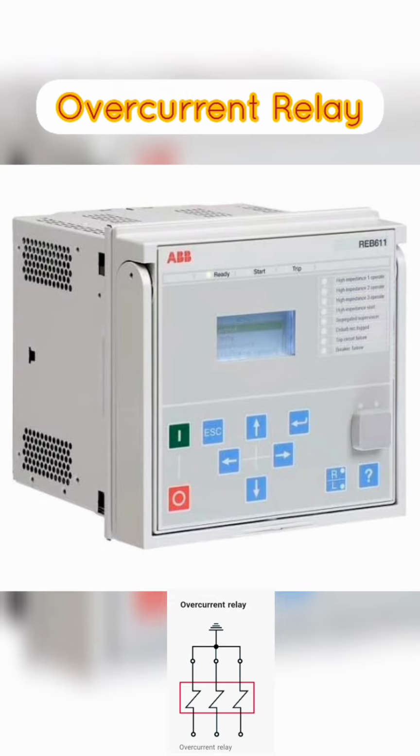Next we learn about overcurrent relay. An overcurrent relay is a protective device used in electrical power systems to detect abnormal currents and to trip the associated circuit breakers to isolate the faulted equipment or system. The purpose of an overcurrent relay is to limit the duration of the fault and minimize damage to the equipment, as well as to protect personnel from electric shock.